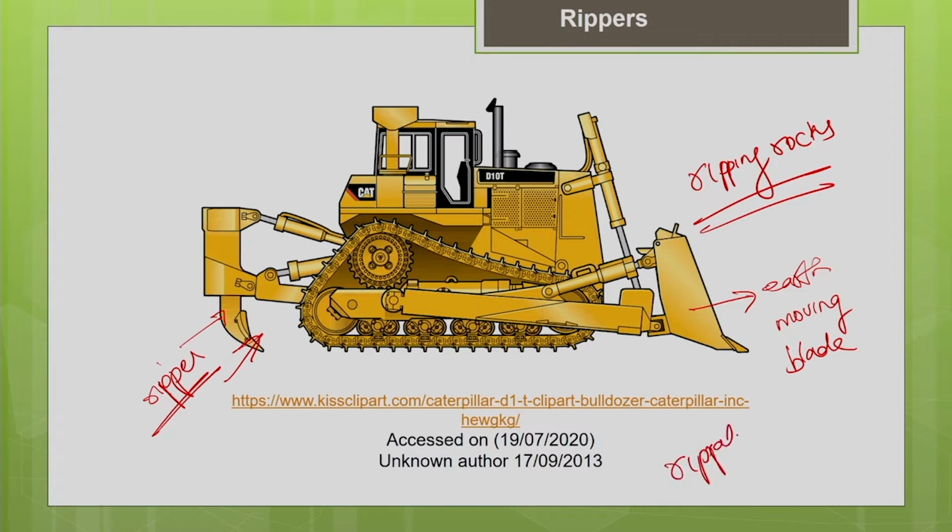You have to check the rippability of your rock. For that, there are some special methods like seismographic techniques. We are not going to discuss that in this particular lecture. Based upon that, you can check whether the rock is rippable or not. Once you know that the rock is rippable, you can use this technique for ripping it. That will result in huge saving in the cost. Similarly, you can use it also for ripping old pavements, so it can have different applications.